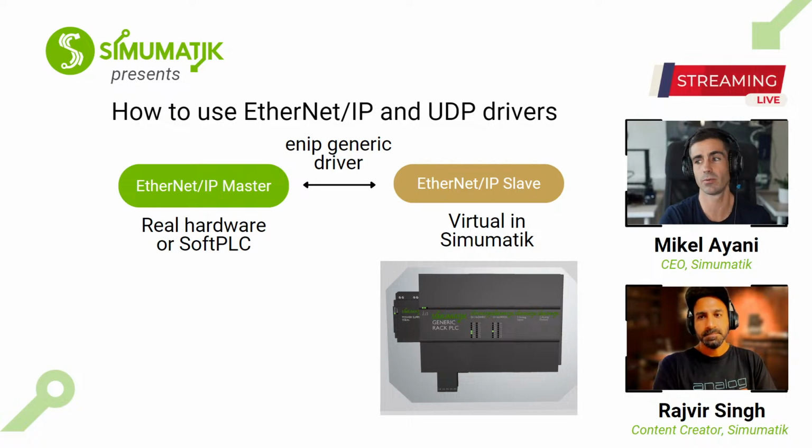So you have a master, which usually is the PLC or the CPU, which wants to communicate with several slaves and gather information and send information to them. So in a master-slave topology, it's the master, the PLC, which takes the initiative, or takes the first step and starts the communication with the others. Okay, it sends telegrams and receives telegrams. So that's the main difference.